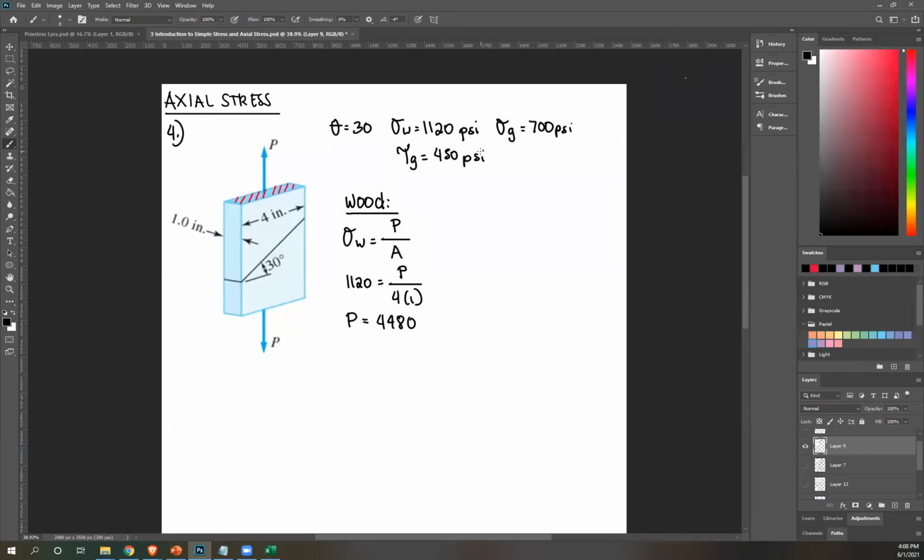And the unit, we're using psi. By the way, you have to make sure your units are consistent. Stress is psi, pounds per square inch. Our area is also in square inches, inch times inch. Therefore, this unit is pounds. So inches will cancel out. This is pounds. So that's not the answer yet. Again, that is one option.